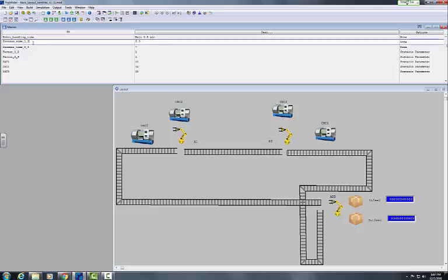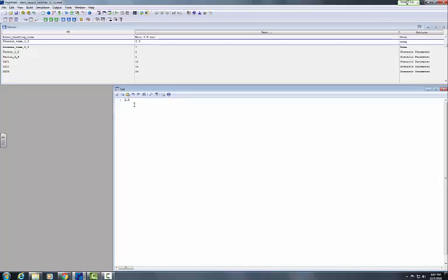Process time 1 and 2 is basically the process time of the CNC machines 1 and 2, and we have set it to be 2.5 minutes in this case. So note that this can be a deterministic number as 2.5, and the default unit in ProModel is minutes, so you need not write minutes, or it can be a normal distribution of 2.5 mean and 0.2 standard deviation, right?